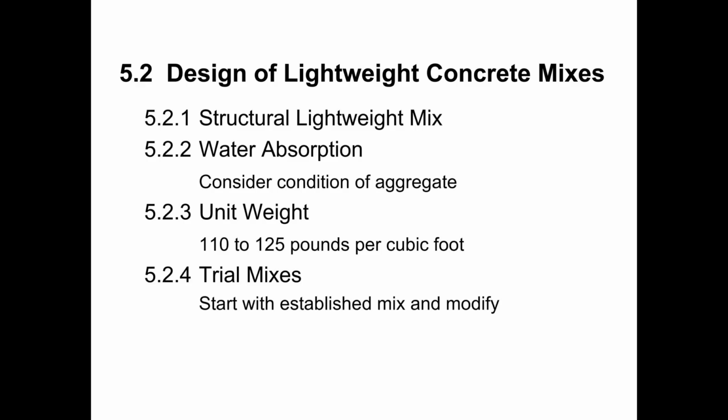So the aggregate supplier should have a lot of information regarding mix designs that their aggregate has been used in. And so oftentimes they can give you a starting point mix design that will be just as good, if not better, than the starting point mix design that you would develop on your own using the tables from MNL 103 and ACI 211.2.